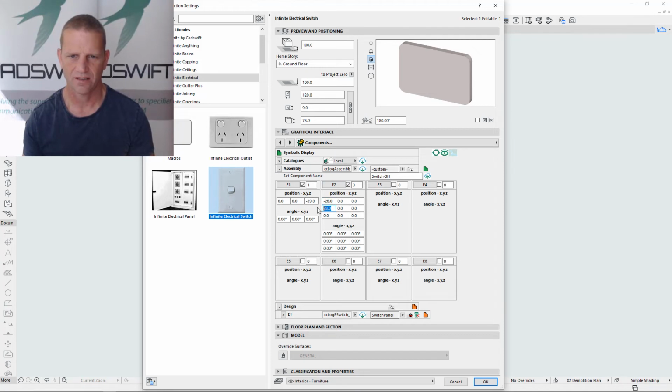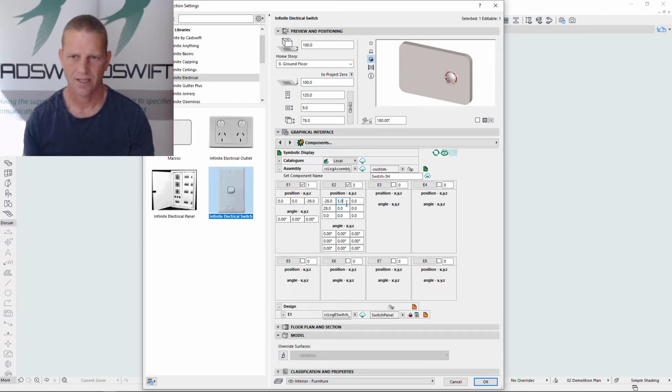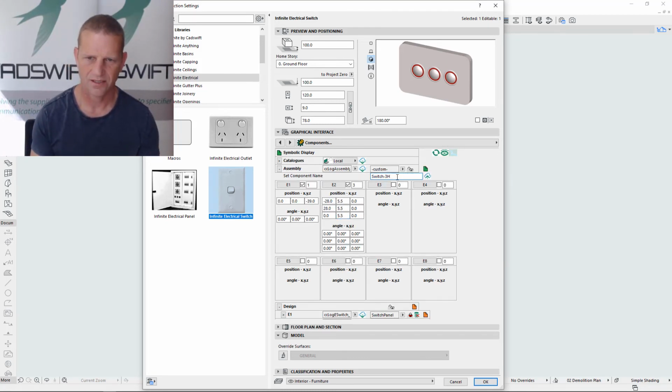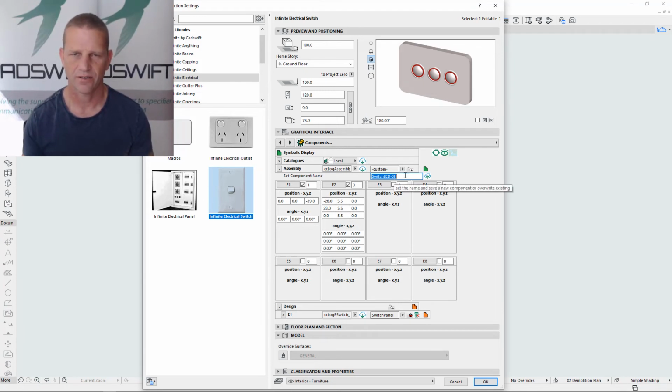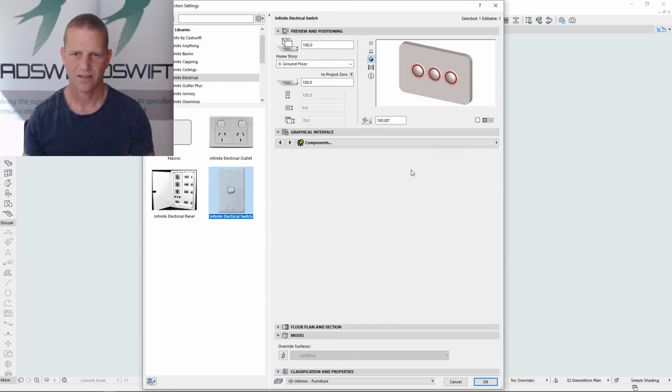So you can see we've got their X and Y positions. So we'll do the Z position here as well, or Y in this case. So we had it at 9, we're going to -4, so let's do 5. Okay, you can see it just breaking through the surface there, so let's do 5.5. Now we can save this as switch 3H, or maybe we call it switch LED, because we did call these switches switch LED, so switch LED 3 horizontal makes sense, and upload, download, and lock.